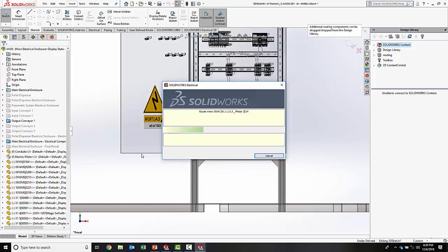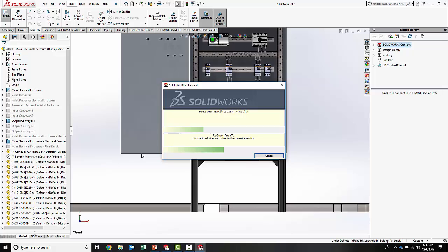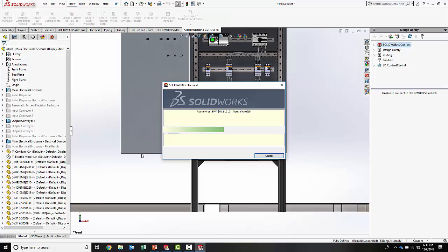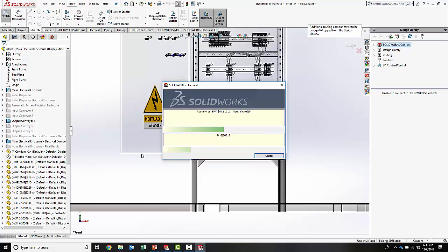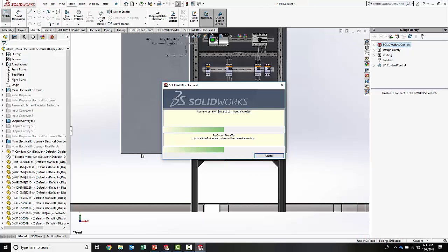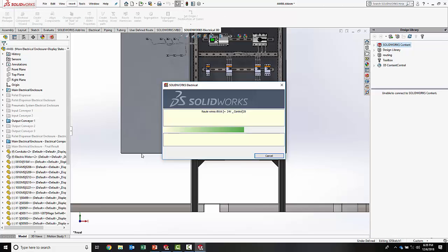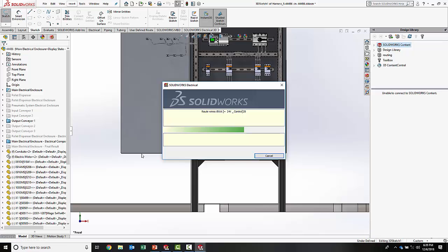With electrical, you can actually create a 3D sketch on your assembly for where the wires should route. So you actually tell it how to route, and then it goes and follows that path to create that route for you, one wire at a time, one style at a time. It's kind of awesome, which is really cool when you think about it. You can create assembly instructions for one type of wire by saying, here's what you need to do.